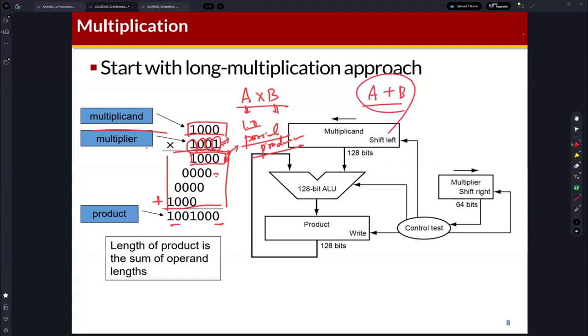But for multiplication, multiple partial products are generated, and then we need to perform additions for these partial products. So that's why multiplication is more complex than addition. And also the size: the size of a multiplier engine is larger than the size of an adder, right?